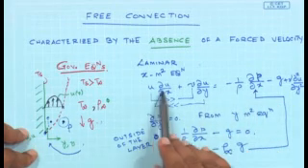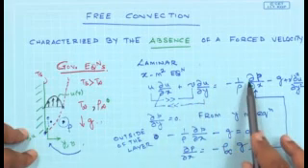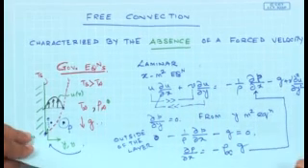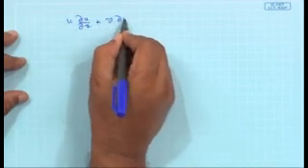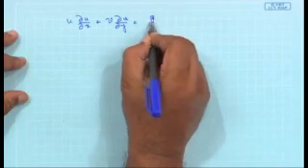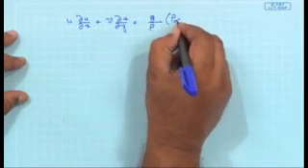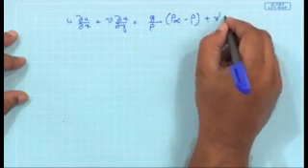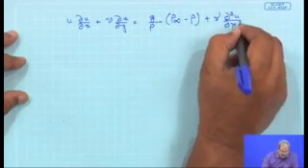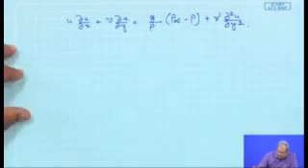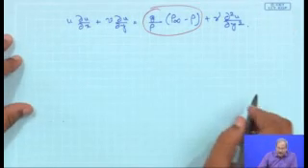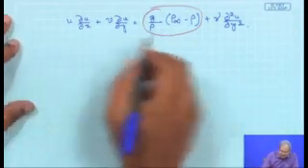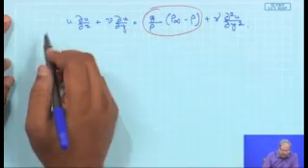If I put this equation back in here, then the left hand side will remain the same. The right hand side, these two terms can therefore be clubbed together to give the equation as u ∂u/∂x + v ∂u/∂y = g (ρ∞ - ρ)/ρ + ν ∂²u/∂y². Now this is the term, therefore, which is the body force which is acting on the fluid under natural convection conditions.